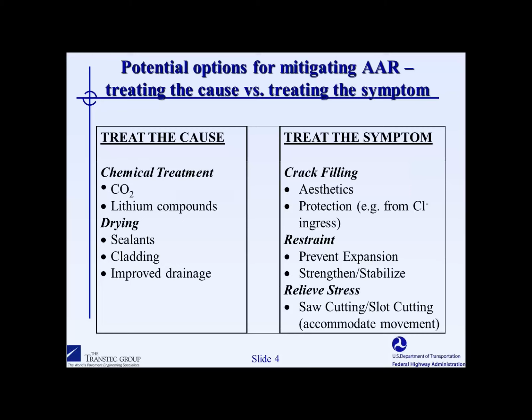This is typically done with a flexible caulking material, and it's often done for aesthetics or particularly to try to protect the concrete from chlorides penetrating in, or perhaps from preventing water from penetrating in cold environments where freeze-thaw might create some issues in the cracked portions of the concrete.